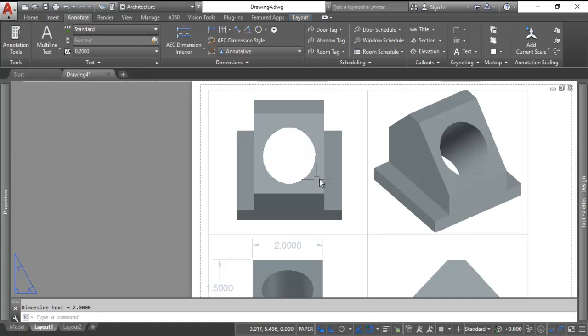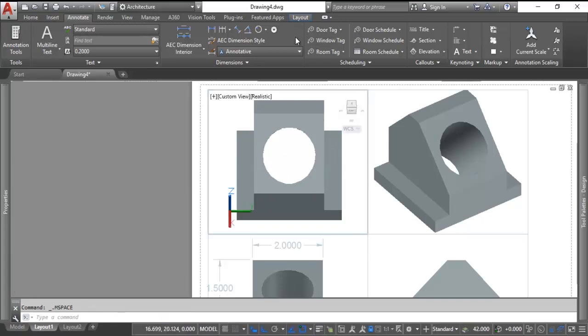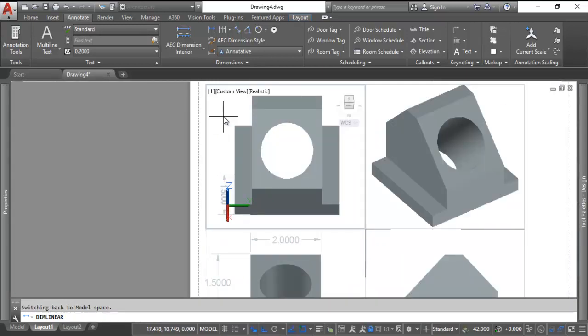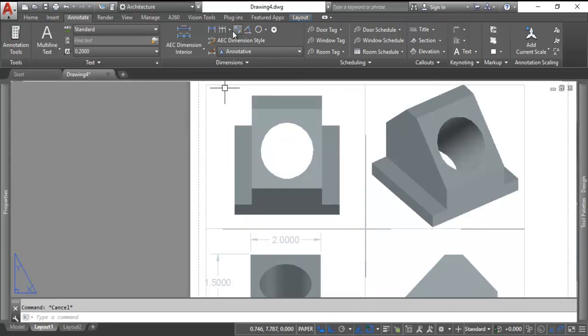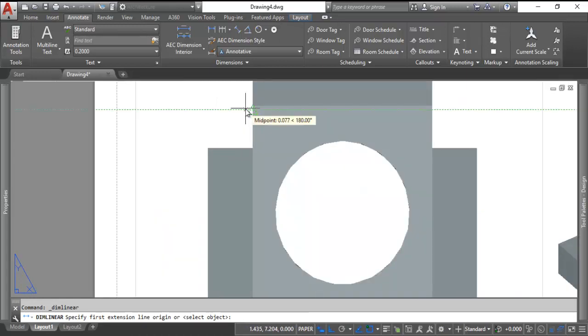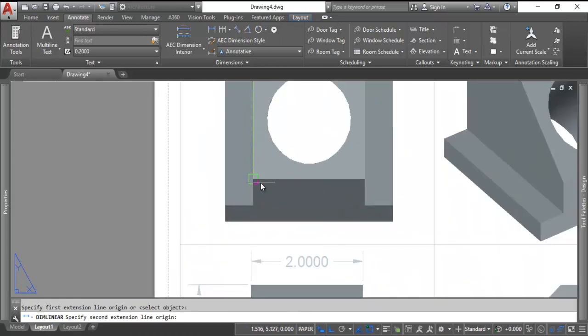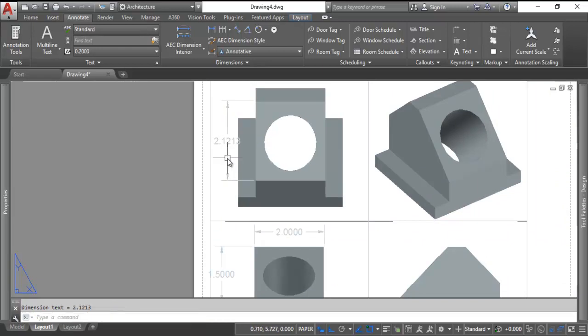And it's kind of interesting as I look at this view here, the way that I created that, it created an auxiliary view, which I did by accident, but when I hit top view it gave me an auxiliary view. So you're seeing a view perpendicular with this face, which is what we wanted. So on the auxiliary view we can add that dimension that we didn't have in the textbook, which is corner to corner. Oops, but I can't do it in the viewport, sorry. We're doing these dimensions in paperspace, so make sure you haven't activated your viewport by double clicking. So that's that odd dimension that we didn't know.